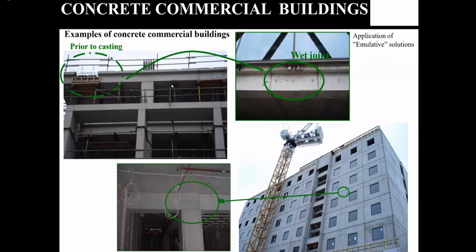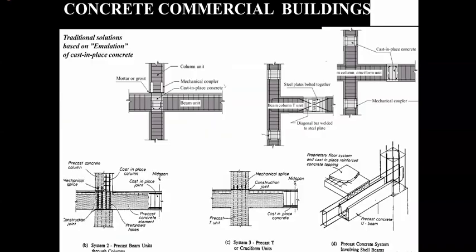It's quite fast construction, and in New Zealand most of the time the concrete is always precast. There's nothing like on site. Everything comes from the fabrication yard. You simply erect it, and you join either using cast in situ joints or steel connections, right? There are many techniques for how you join your precast elements. The cast in situ joint can be at the beam column location, like what my cursor is pointing towards, or at the center of the beam, or it could be using a steel plate and bolted joints. There are many different varieties for how you can achieve a monolithic system using precast elements.